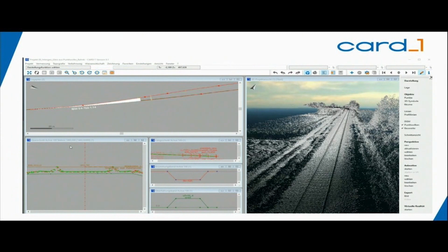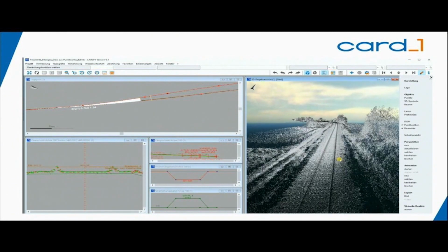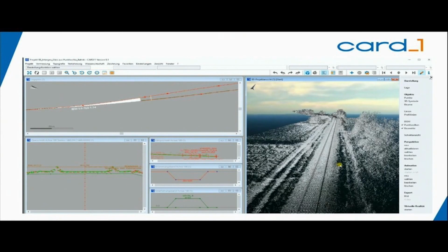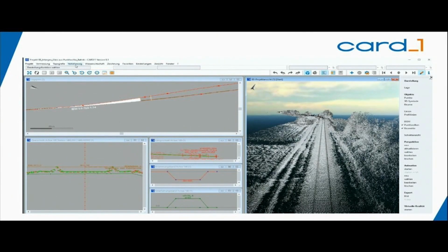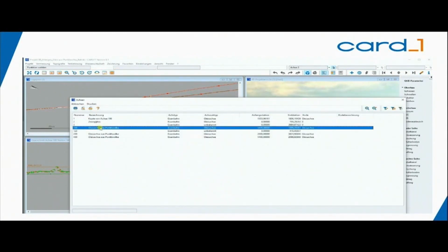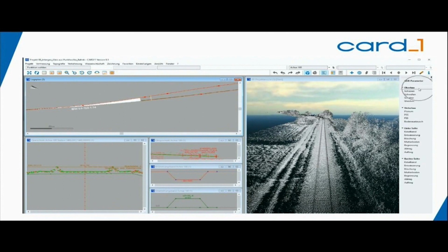So now I increased the 3D project view on the right, and we have enabled the point cloud data. He's moving around a little bit, showing you that everything is okay. And then we start from Verkehrsweg, route planning, the module called BIM Bahnkörper. We will not define new elements now and change them due to lack of time, but you can see the information you just mentioned. Important is to choose the just created axis 100.